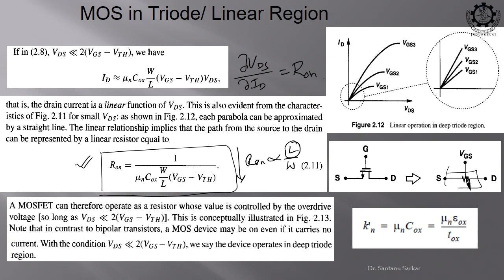If it is on, its resistance should be 0, if it is off, its resistance is high, right. In off state, cutoff is taking care of high resistance, but in on state you should model it so that its R on is low. So, as its R on is proportional to L by W, you should choose L minimum.